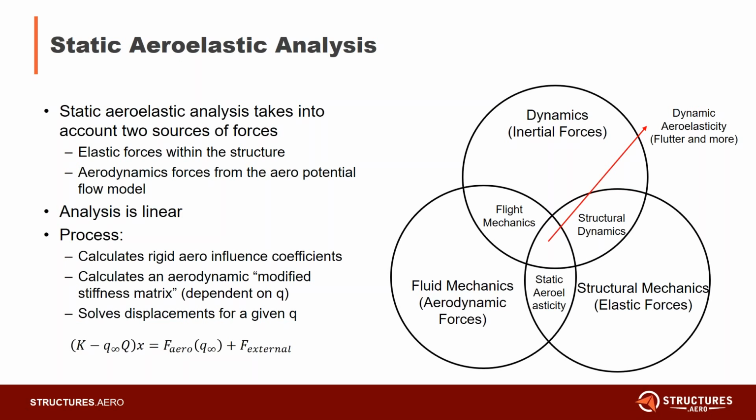Those of you who are familiar with buckling analysis, it's kind of like your geometric stiffness matrix. This is going to add to your traditional stiffness matrix, and again, often like buckling, this will soften your structure in a lot of places due to aerodynamic forces. And then it also calculates the rigid forces due to your aerodynamic model. So this should give you all a rough idea as to what's going on under the hood.